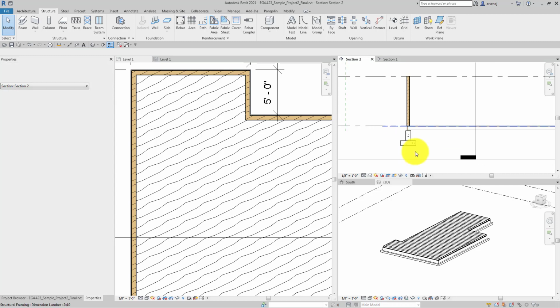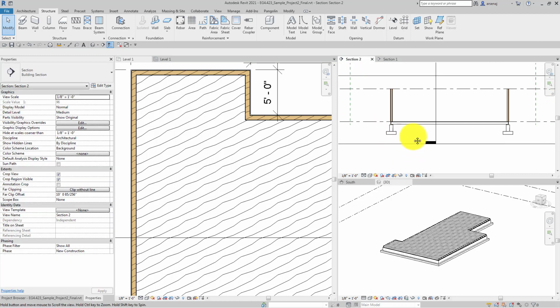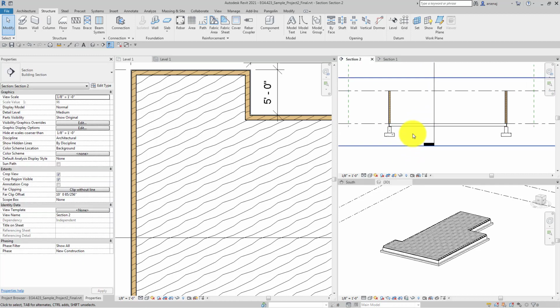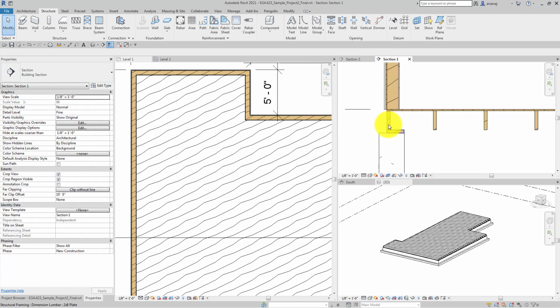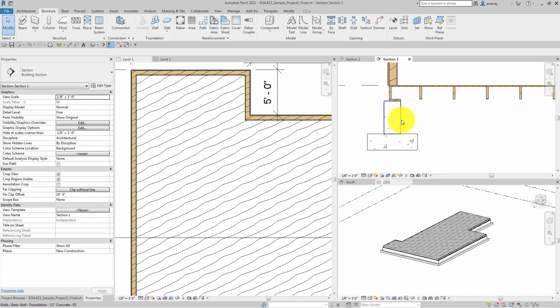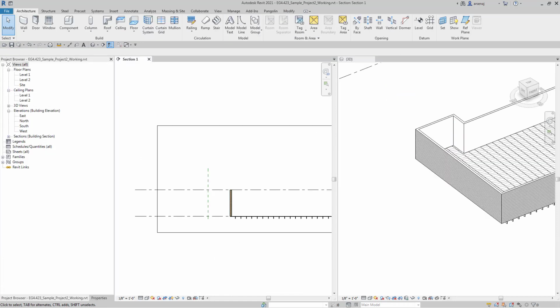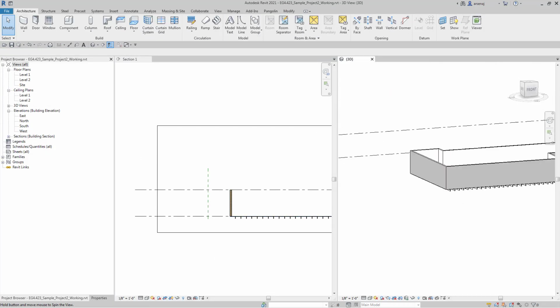So we're going to finish up getting our preliminary foundation set by adding this exterior header joist, this plate that's going to sit on top of the foundation wall, and then the footing.